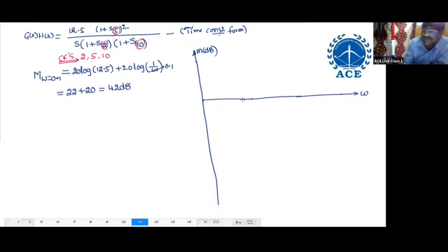Represent the corner frequencies: first one 2, second one 5, third one 10. Next, start with 0.1. At 0.1, what is the magnitude? 42. At 0.1, I'll take plus 42.